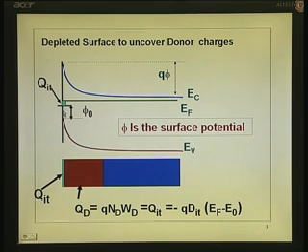So, when D_it tends closer and closer to infinity, which is not realistic, but when it becomes very large, E_f almost matches E_0. That is what is known as Fermi level pinning. The Fermi level tends to pin to the E_0 level. It will not pin exactly, but it will go as close as possible, so that a small gap between E_f and E_0 supplies enough negative charge to the depletion layer.